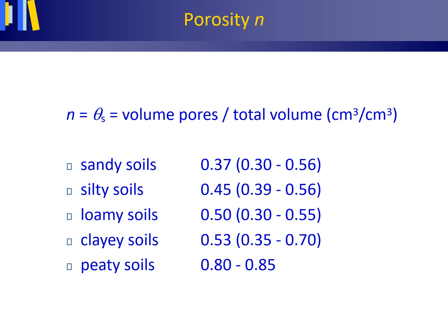Typical values for different types of soil are as indicated here. It is hard to perform hydrological tests on clay, as these may swell or shrink depending on the moisture content, and also on peat because of its high porosity. Please note the large range of porosity values for different types of soil given in brackets, and the large average value for the porosity N of clay as compared to sand.